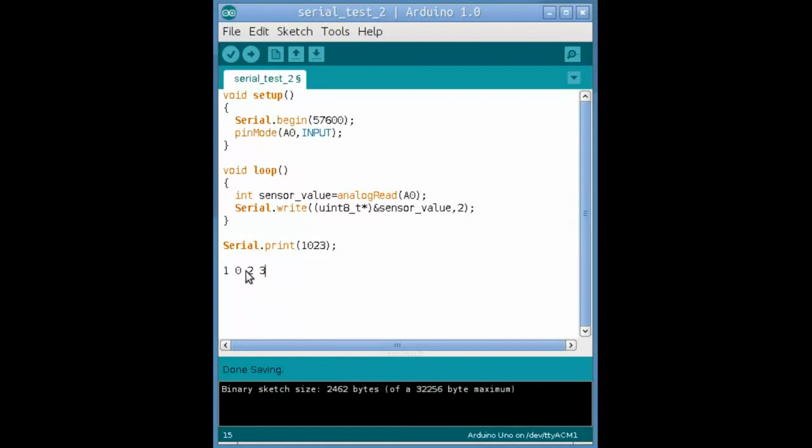The point is that we're going to have to do some math, subtract some numbers, and then multiply by the place it's in. So if it's a 1 and it's in the 4th place, that's 1,000, so you multiply whatever this number is times 1,000. It's really complicated, and we just don't want to do that. Instead, with Serial.write, we're only sending 2 bytes. If our value was 1024, it would look like this: 04 00, I believe.